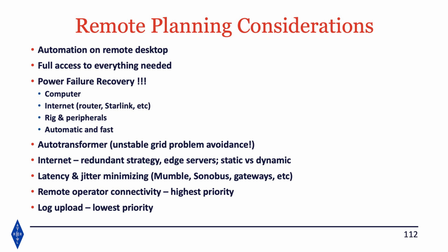Another device which is critically important that we use is what's called an auto transformer. And the reason why, the 220 volt power in Malawi changes from 159 to 260. This does not treat your equipment well. So an auto transformer makes that 220 constantly, and they're available.